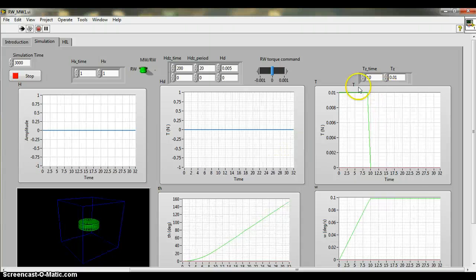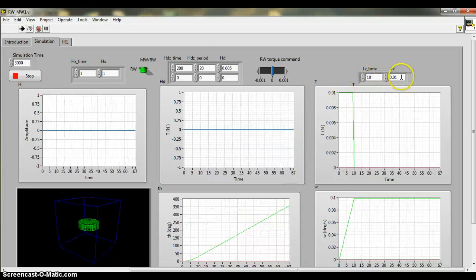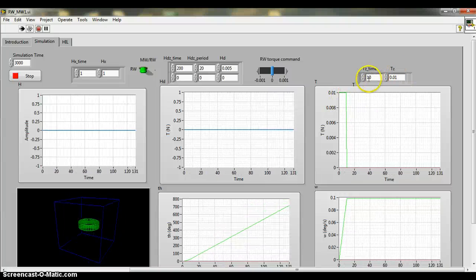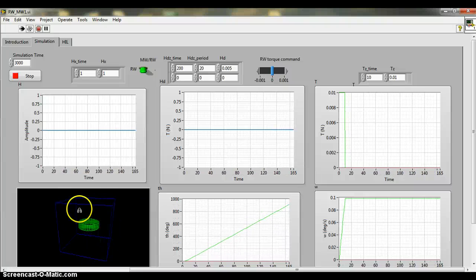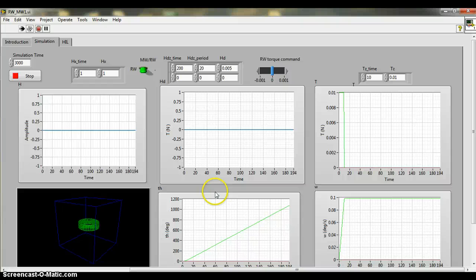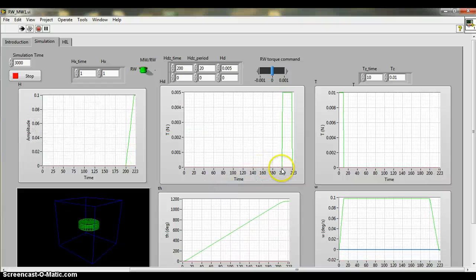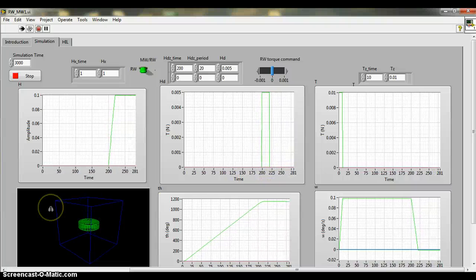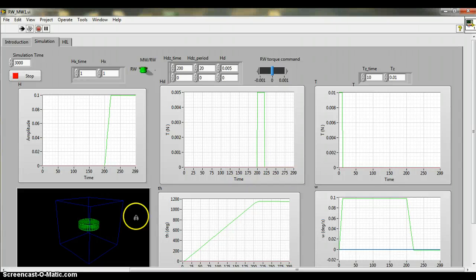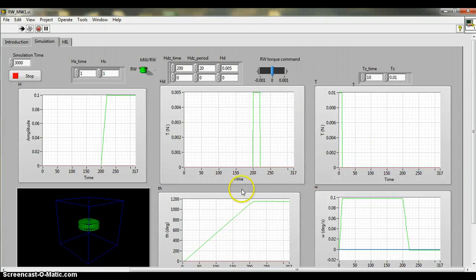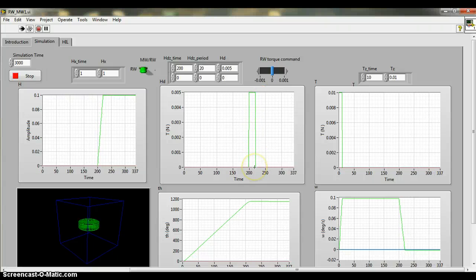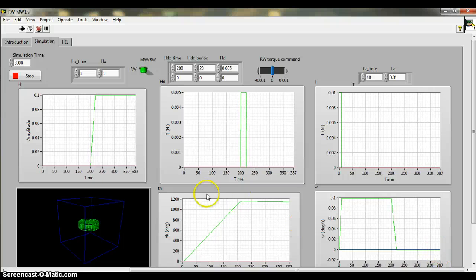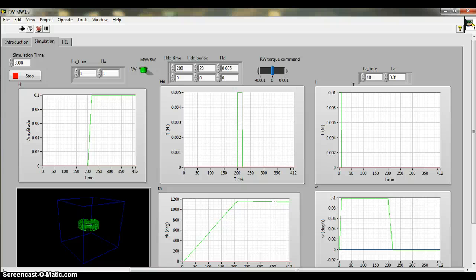As we see the effects of applying the external disturbance torque, the disturbance torque applied in the positive direction, so the satellite starts to rotate in the positive direction. At 200 seconds, the reaction wheel works, so it compensates the effect of the external disturbance. As we see here, after applying the reaction wheel torque, the angular velocity of satellite becomes 0, and the angles of satellite become constant.